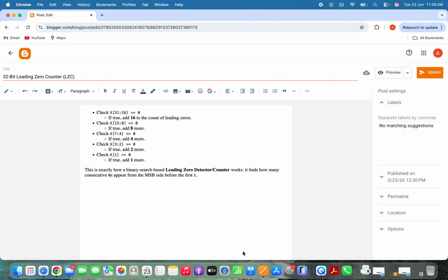Hi everyone, in this video we are going to learn about the leading zero detector and understand how it works using a binary search approach. A leading zero detector is a combinational circuit that counts the number of consecutive zeros starting from the MSB until the first logic one is encountered.